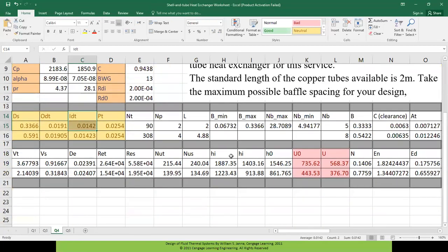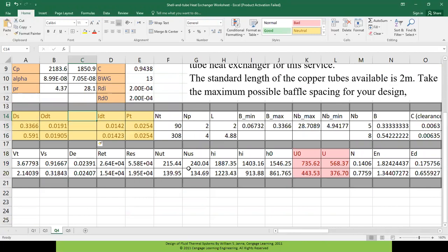But we have chosen 13, but we chose the outer diameter to be 19.1, not 25.4. The outer diameter is 3/4 inch. The 1 inch is the pitch. There are two sizes, and there may be more sizes, but you have to choose your size, 3/4 inch.